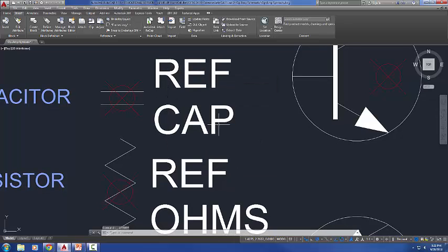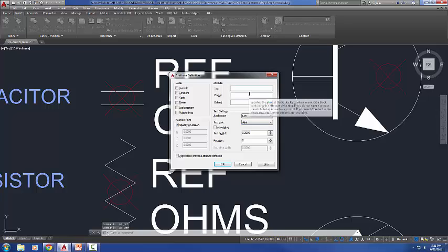I'm going to snap to this corner here for my new origin. Next it's asking me for the positive X direction, so I'll snap there. Now for my new positive Y direction, I'll snap right here. Oops, and notice my whole screen changed, and now what was the east elevation is now pointing straight up.